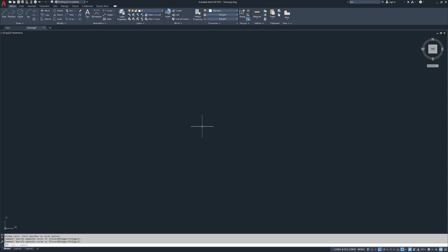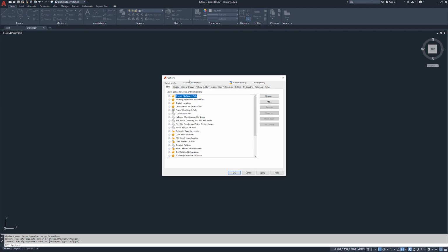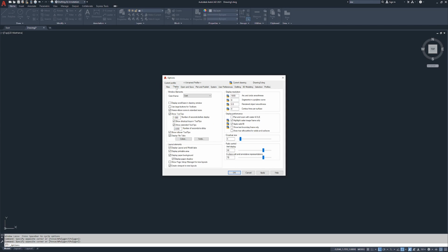There's one more thing I want to show you. When you start AutoCAD, your background is going to be this kind of gross, dark gray, which is hard on the eyes after a while. So what you want to do to fix this background is go up to your A, click the A, go to your options. These are the AutoCAD software options. Ignore the Files tab. We're not going to ever touch anything inside of there. I take that back. There might be one or two things that we do inside of here. What we want is the Display tab. Click on the Display tab.